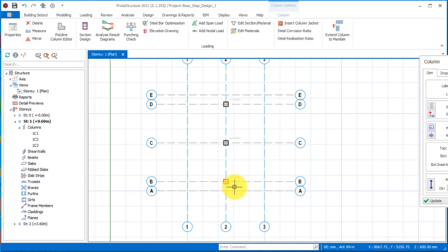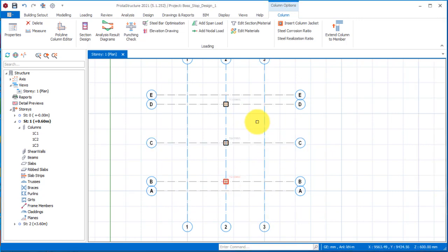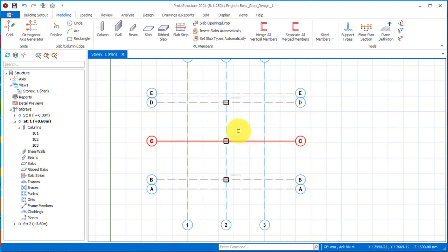I release my hand to have the column placed just like this automatically. Alright, after which we have to click on close to close this columns property dialog. Then I have successfully inserted my columns. Alright, so I will now navigate to the 3D.